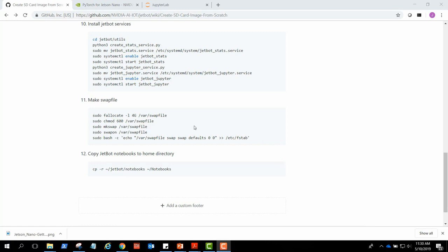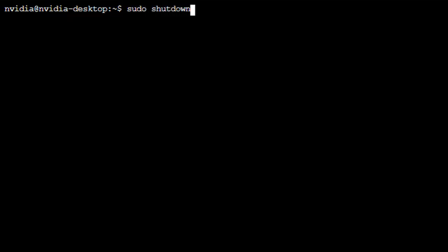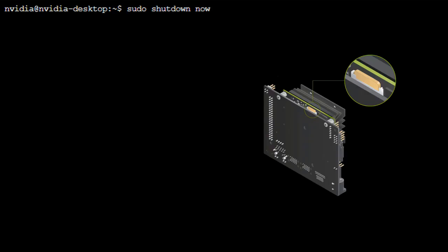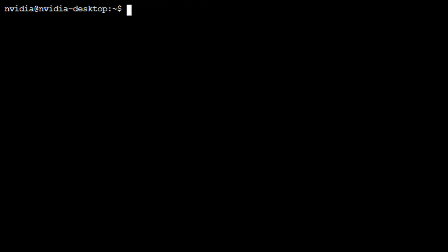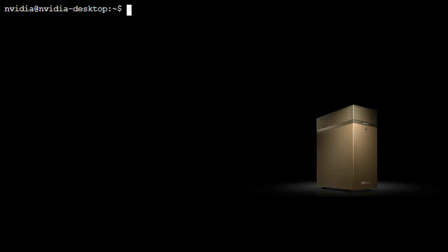Once you have your Jetson Nano configured just how you want it, you can create a snapshot of the SD card image that you can compress to use in other copies of your project or so other users can easily use your project. To do this, you would first shut down the Jetson Nano and remove the SD card from the SD card slot. Then, you would plug the SD card into a Linux desktop machine and check where the device is located by typing sudo fdisk -l. Assuming the SD card is located at /dev/sdb, we could record a snapshot of the SD card image to a file by typing the following command.